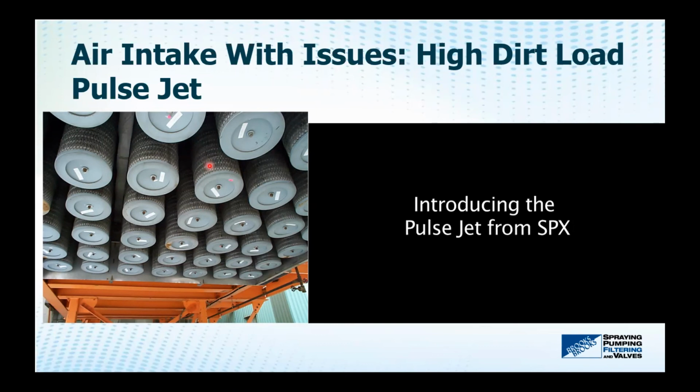So what you were seeing there is a reverse flow pulse of compressed air, and the shock it creates as it goes through the media actually loosens and causes the debris to fall below the filter. So sometimes customers have a container there where they can catch the dust.